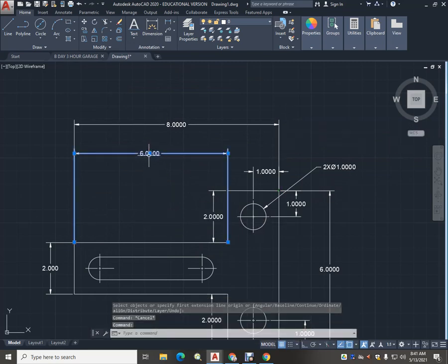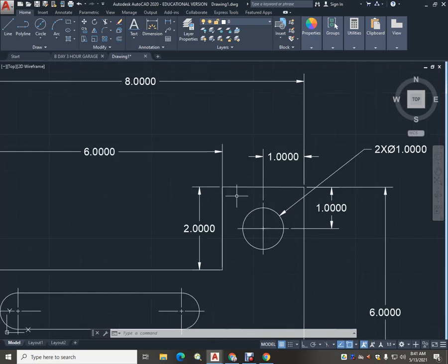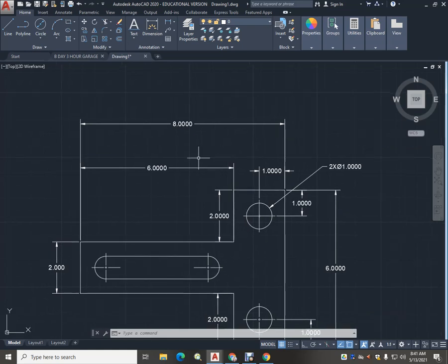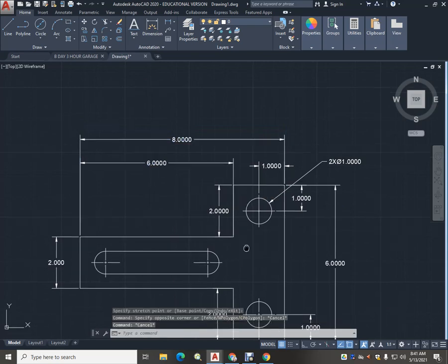So as a machinist now, I can say, okay, you're telling me that the most important spot is that I need to get this right between this shoulder and this one as being 6, and then I can make the overall part 8. So this particular piece in here is not as sensitive, so I can go ahead and do that for you, which can be easily done, and then worry about where these holes are located.